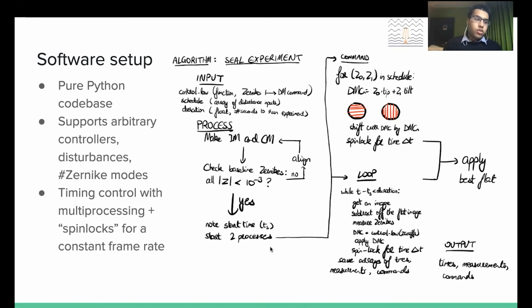And we make use of that so that things happen on a set schedule and they don't drift. So we're running at 100 Hertz, which means we run from 0 until the loop ends, and then we spin lock until time 0.01. We run until the loop ends, spin lock till 0.02, and so on, so that we don't have drift over time and things actually happen when we say they'll happen. This is very important for a state space model because everything depends on the underlying model moving forward only 0.01 seconds when the loop moves forward that much.